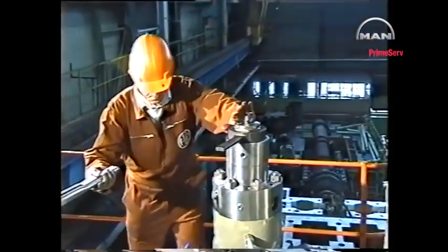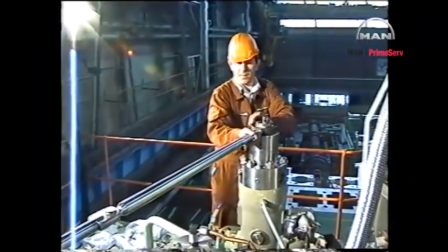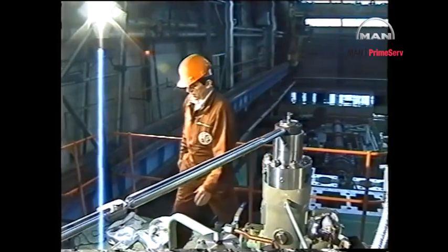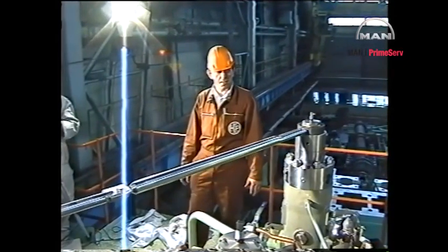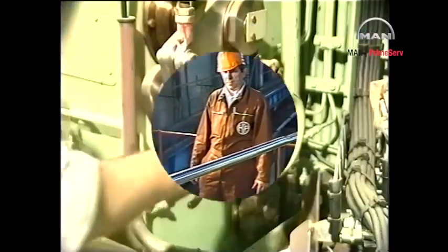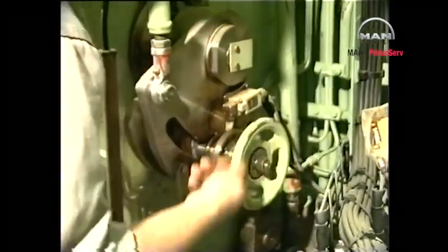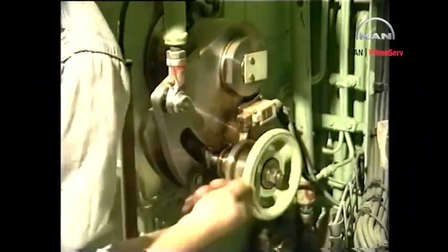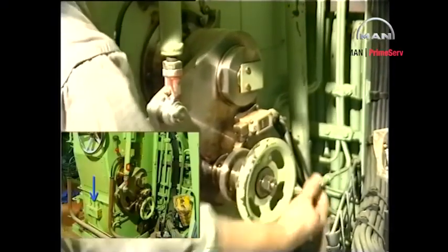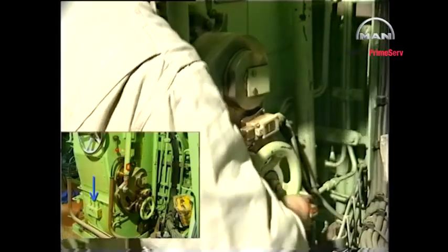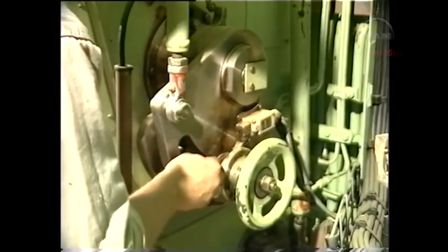Tighten the puncture valve to the torque stated in the instruction book, Volume 2, Chapter 909, and mount the plug screws, cover and control air pipe. Finally, change over to normal engine control. Make sure that the VIT system changeover valve is properly connected.